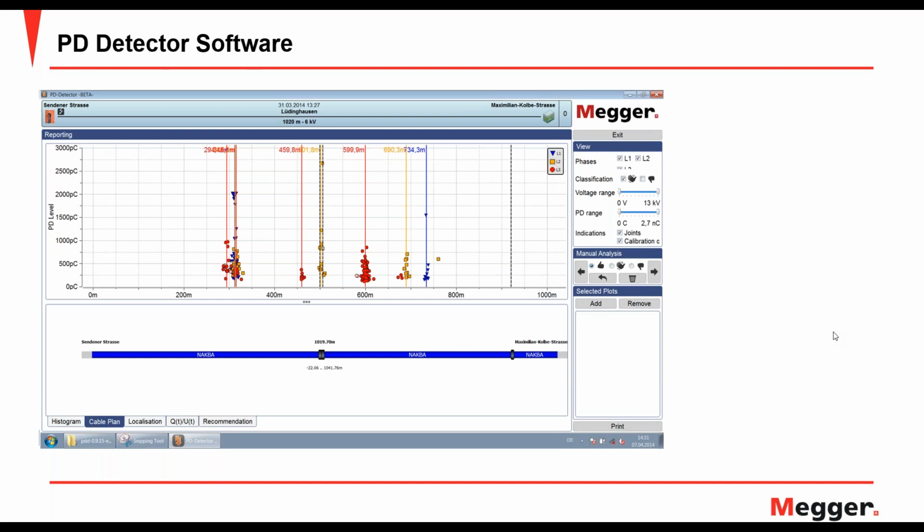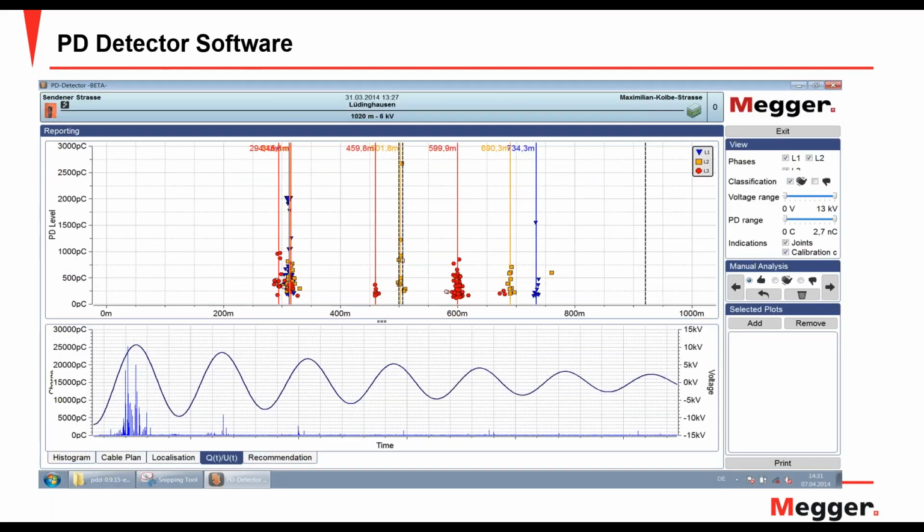And the situation like this, as I go right back to that cable clamping, is if those cables were clamped and over torqued, then you can cause that inhomogeneous distribution of field and cause PD activity to take place. And it was done on all 3 phases. So this is something that could be representative of a condition like that, where you may cause a defect by over torquing your cable. This is the same measurement, but just shows the damped AC applied wave on the bottom.